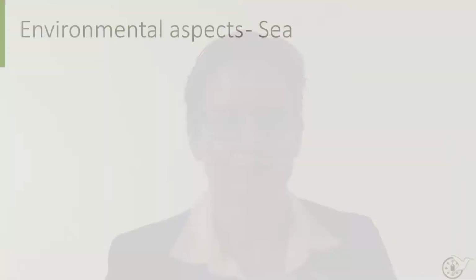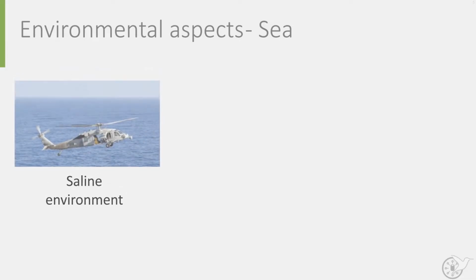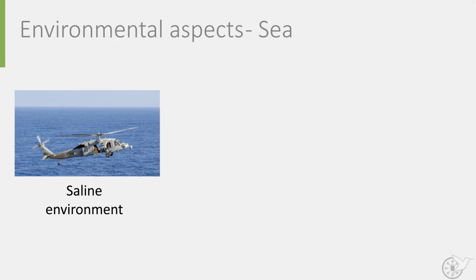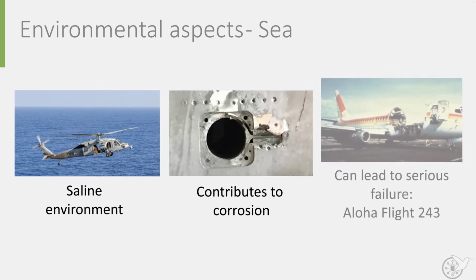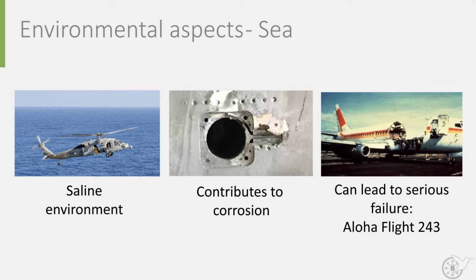So let's zoom in on a helicopter in a saline environment. For most metal alloys, the combination of moisture and salt forms an aggressive environment that leads to corrosion. Corrosion is an electrochemical reaction that metallic atoms have with oxidants and can be accelerated by the presence of water. This makes corrosion a real issue in metals and can lead to disaster, as was the case for the ill-fated Aloha Airlines Flight 243 that lost part of its upper fuselage during the flight.